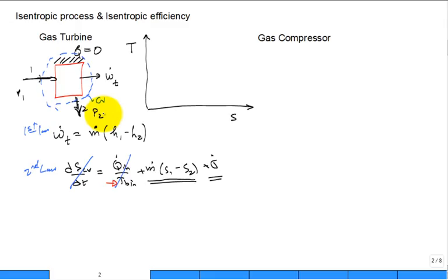All right, so this is a line, constant pressure on a TS diagram in the ideal gas region. Forget the dome. If you want to tuck the dome in somewhere, put it way down, out of the way. There's the dome, out of the way. No more dome, get it out. Okay, and this is going to be a line of high pressure, P1, line of low pressure, P2. So we're coming in at this point, state 1.